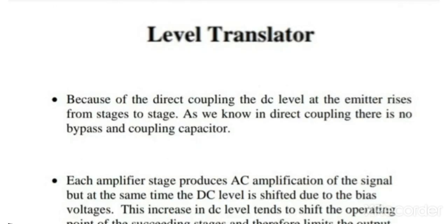Now we will discuss what is level translator. We know that differential amplifier is the basic building block of operational amplifier. There are many stages in operational amplifier. The first stage is dual input balanced output differential amplifier, and the second stage is dual input unbalanced output differential amplifier.